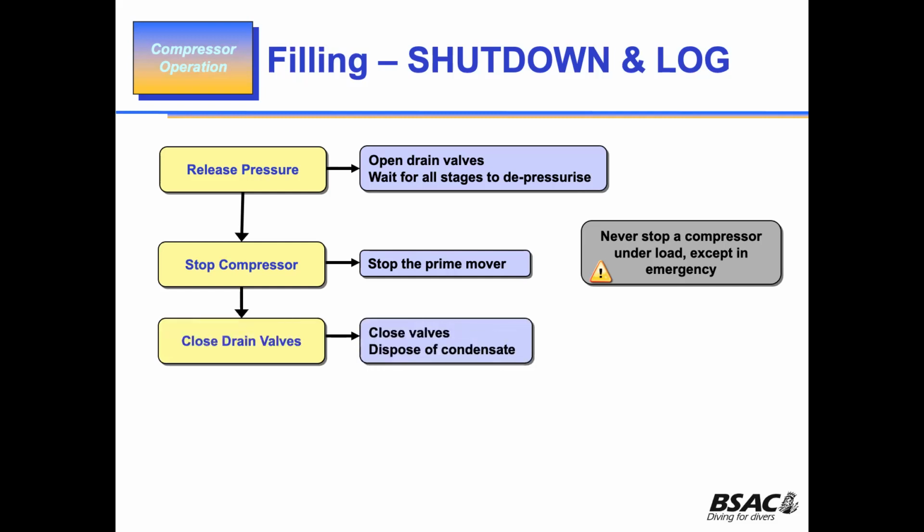Close all the drain valves. As I said, you don't want air being sucked in, because that air is going to have moisture in it. Close all valves. Dispose of condensate. Well, normally you've blown it all over the concrete anyhow, so there's no disposal. It's already done.